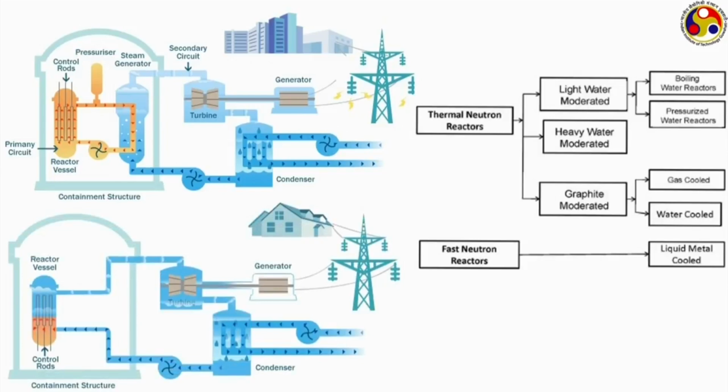And this is a boiling water reactor. In case of a boiling water reactor, the water or the fluid is allowed to boil and gets converted to steam, or I should say a part of that water gets converted to steam, and the steam is taken through the subsequent processing in the form of turbine and expansion in the turbine and condenser and pump, and again back to the core in the form of recirculation.